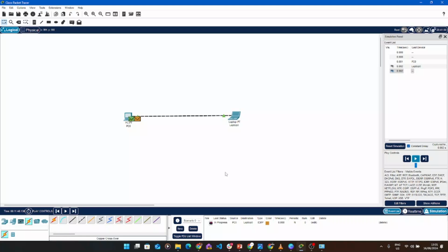So there are different ways the cables are arranged in colors, right? For example, for the copper straight through, the color arrangement will be orange and white, orange, green and white, blue, blue and white, green, brown and white, and brown. So those are how the eight wires will be arranged on both ends. If you watch that video, you see I showed an example of that cable, an internet cable. This is just a simulation of what it looks like.